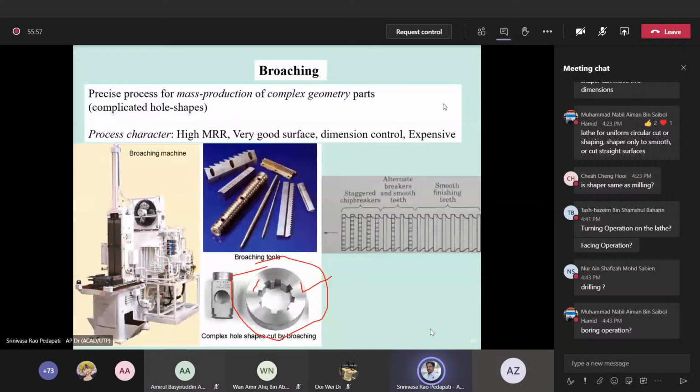So if you want mass production and want to make many objects, you can do it with a lathe machine, but you require many tools: a drilling tool, a boring tool, a facing tool, a turning tool, and then reaming to extend that hole. So many tools are required, so many operations to be performed. Yes, it is possible with a lathe machine, but with some limitations and also a very slow production rate because you have to change the tools.